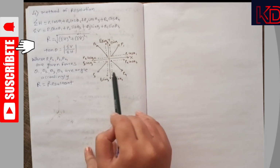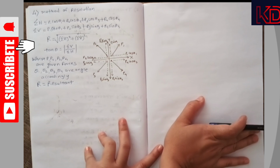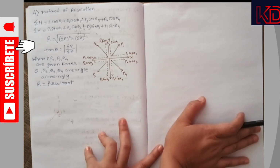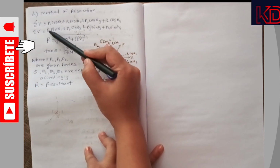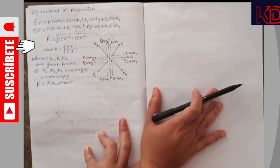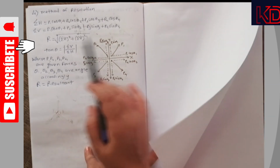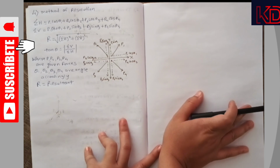By drawing this figure, I came to one conclusion, that the summation of H, that is horizontal forces, is equal to P1 cos theta 1 plus P2 cos theta 2. It is very easy, isn't it? Then the summation of vertical forces is equal to P1 sin theta 1 plus P2 sin theta 2. Then by calculating these two things, we can calculate the resultant simply by putting them inside the square root, same as calculating the hypotenuse of a triangle. And tan theta is nothing but summation of V divided by summation of H. We can calculate tan theta, the overall angle.